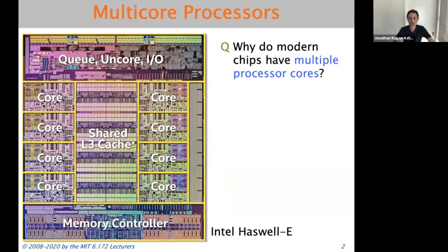And a modern processor chip generally combines many independent cores, like you can see in the floor plan diagram of this Haswell E processor. In this case, we can see 8 of them here, with potentially some shared cache memory. That's what you see in the middle in this case. And usually a whole bunch of other logic, accelerators for different kinds of specialized computation, I/O to talk to memory or USB or the network or other things, all packaged up into one big chip.